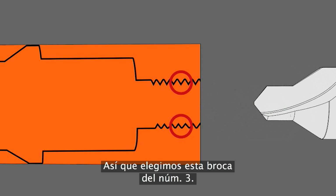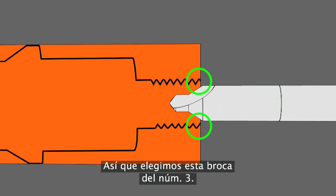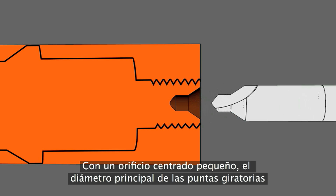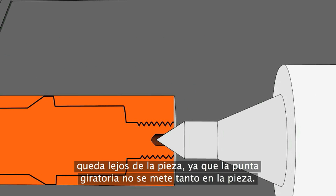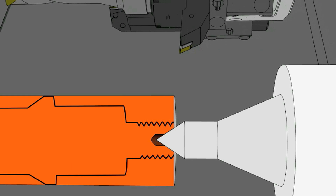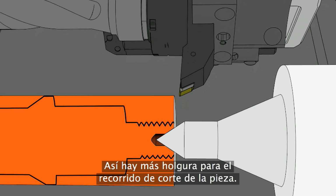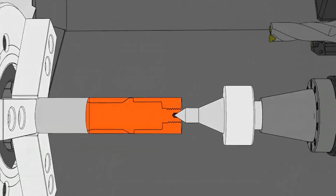So we'll choose this small number 3 center drill. The small center hole will also keep the live center's main diameter farther away from the end of the workpiece, since the live center doesn't sink as deep into the part. This provides additional clearance for the cutting path of the insert.